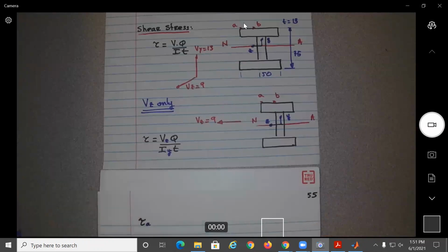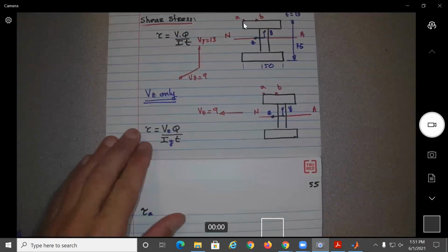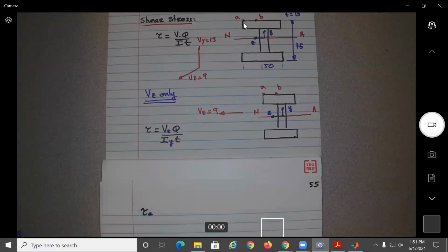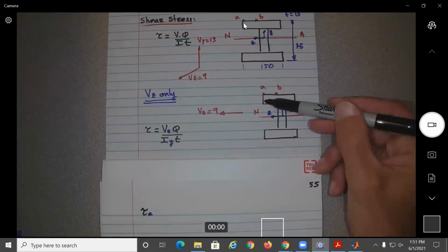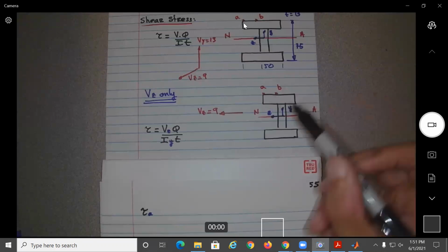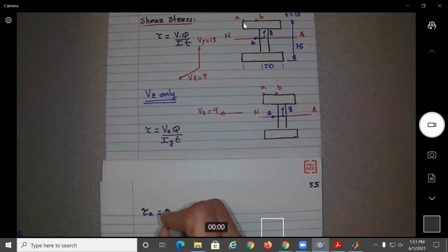Okay, by looking at the figure, let's see if you understood what is shear. What should be the shear at point A? In order to have shear, what do you need? You need to have one surface against the other one, no? In the direction of the Z, is point A rubbing against anything else? Here there is nothing, no? If you look at the surfaces, this surface here is nothing. So the shear at this location is 0.